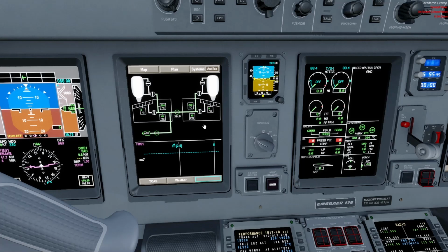Another thing we can't see at the moment in this display is, right now the anti-ice is not operative. We will see that later, but when in flight we would see an ice condition note here, and it would also show here as well. That's happening because of the ice detectors that I showed you at the front. When they're detecting ice, we can see the ice condition both here in the ICAS and here if we go specifically to the systems anti-ice synoptic page.